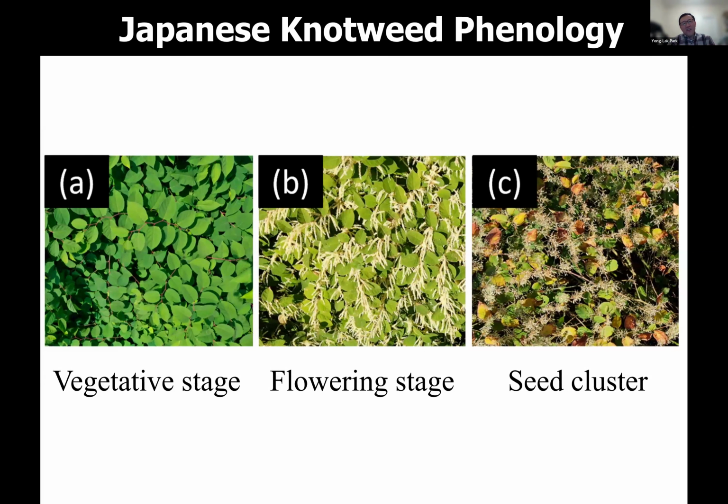Artificial intelligence, right? Machine learning or deep learning. So first thing first, we have to fly a drone anyway to get the images, right? So basically, we flew every 5 meters above the canopy up to 120 meters, in this case, 90 meters. And then we found that up to 20 meters, we can identify Japanese knotweed. Up to 20 meters, we can identify giant knotweed.